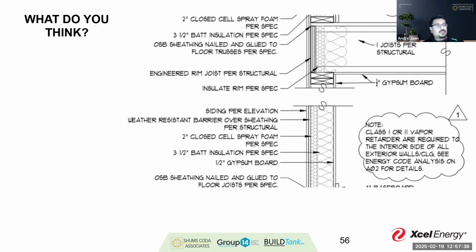Now, I promised you a brief discussion on Joe Lstiburek's thing about that. Basically, I'll sum it up as best as I can, as quickly as I can, which is that if you are going to have two vapor retarders that are significantly strong, like a class 1 and class 1, when the outside is less permeable than the inside, that's what really causes that problem. He does a really good job in an article, that, like I say, if anybody has questions about that, I'd love to send it to you. I think it's a great read.